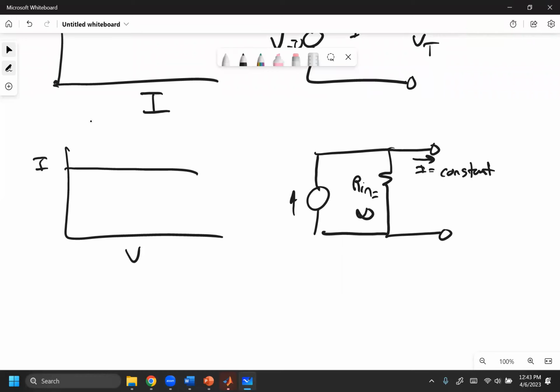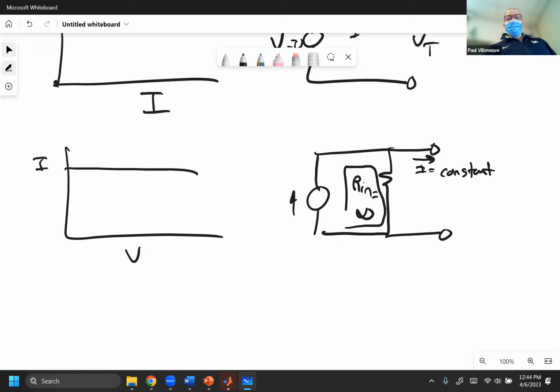If that's equal to infinity, how much current can go through there? As I increase the voltage, I can put it up to 10 million volts, and current should never go through that parallel branch. So when you replace an ideal current source, you replace it with an open circuit. But it's actually replacing it by its internal impedance, which is here.